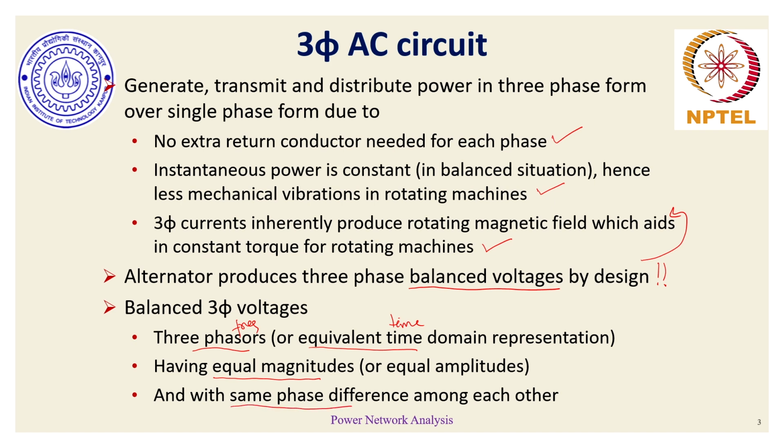That means if I have, let's say, a three-phase system in which I have three phase voltages VA, VB and VC, that's the common convention of how phase A, phase B, phase C are defined in three-phase networks. In certain references, you would also find VR, VY and VB as the common reference, R, Y, B referring to red, yellow and blue. We will try to stick to the small a, b, c notation. So, those discussions are still applicable for VR, VY, VB as well.